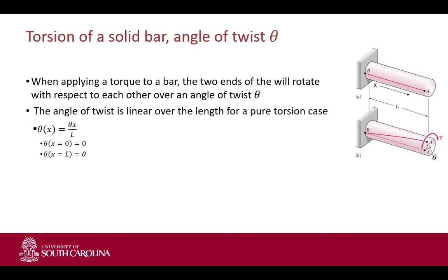Actually, let's continue. We just deal with the solids in this case. Just to continue at a faster pace, we're going to continue on the lecture slides. So what we discussed so far for torsion from a solid bar is we looked at the stress equations, we looked at our compatibility equations, we looked at our boundary conditions, and from those three we got a set of equations that we had to satisfy for our function phi in order to be a valid solution. Another thing that we have to deal with for the solid bar is the twisting angle.